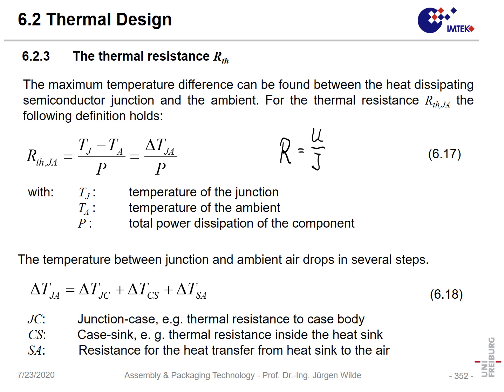Where is the power in the transistor dissipated originally in a PNP transistor, for instance? It's in the PN junction. So here we say where the heat is dissipated is the junction, and where is the heat drained? It is in the ambient. So it's a temperature dependency between the hottest point and the ambient.